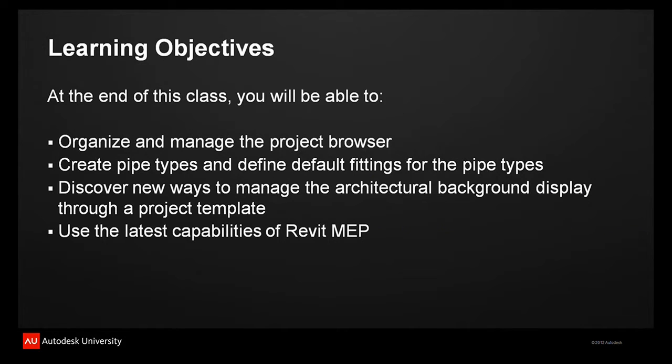I mean, when I set up a project, eventually I always enable work sets, and eventually I'm going to give them that ability starting from a template or from a project. Either way, I'm going to give them that ability. Families that are used in a previous project are already preloaded. I don't know, man. Every project can kind of have their own little needs, especially mechanical, of what equipments are necessary, so I don't want to have anything preloaded, family-wise, in my template.